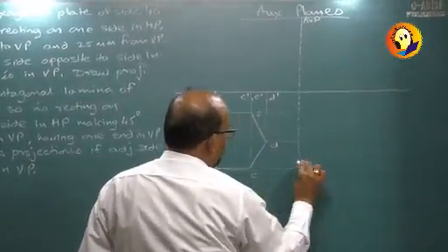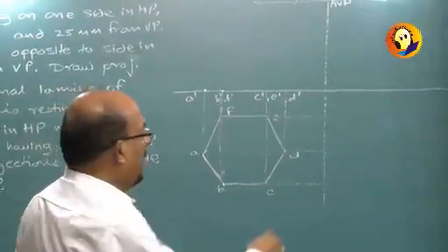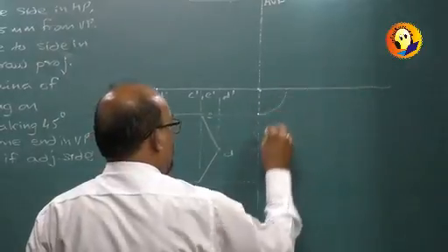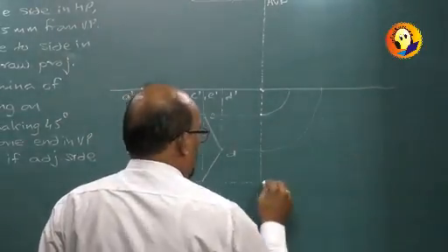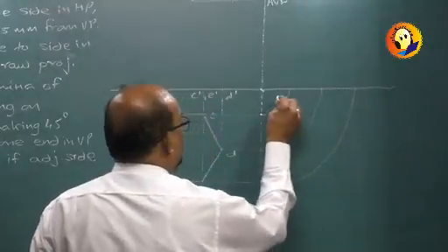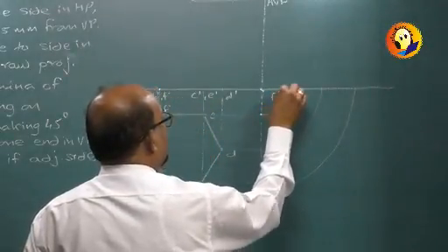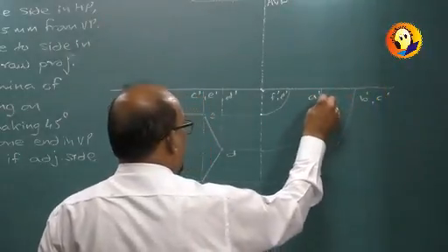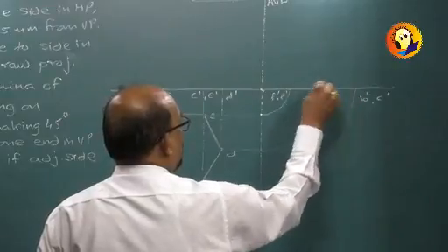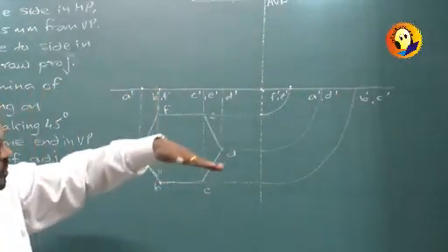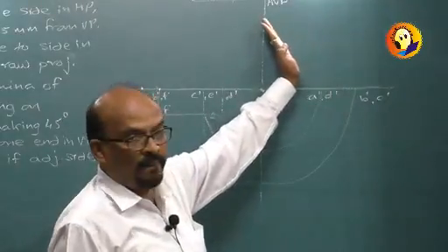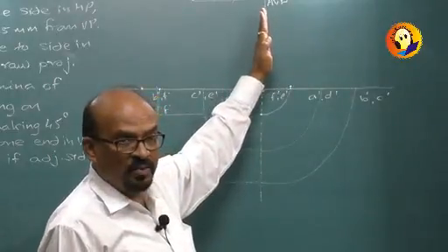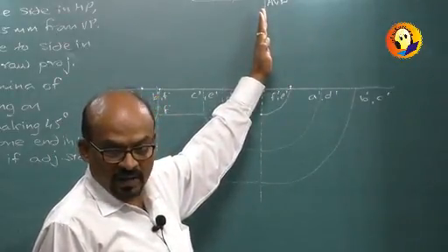and I will take all these points parallel first of all, and then rotate them about this point. And so I get F dash, E dash here, this will be A dash, B dash, C dash and of course D dash, and this is the point about which I should rotate. So in the side view I can rotate it, okay, and this is the vertical plane in the side view.